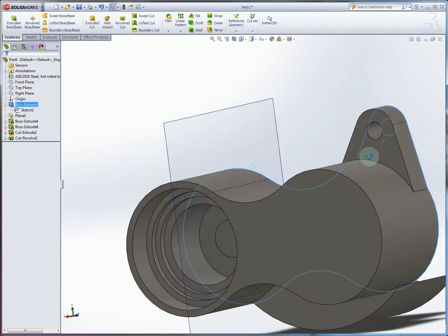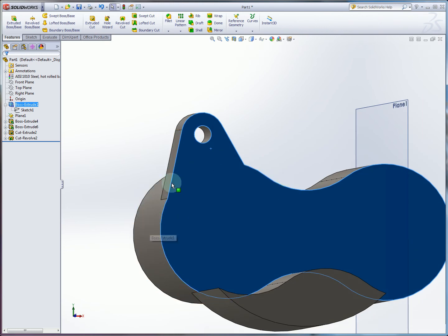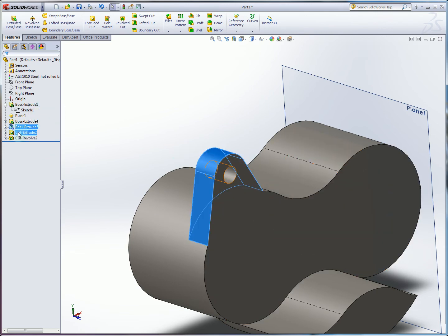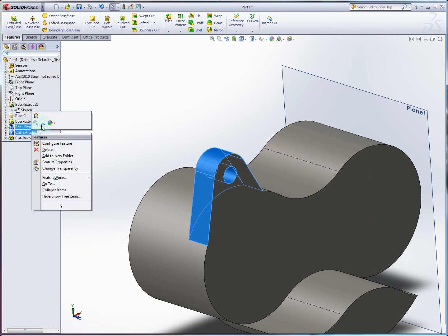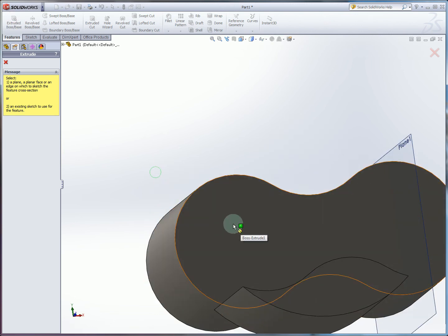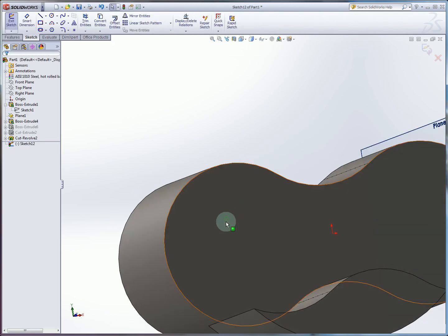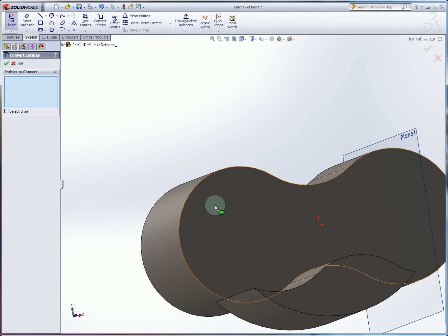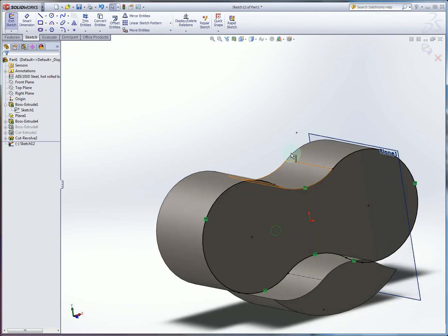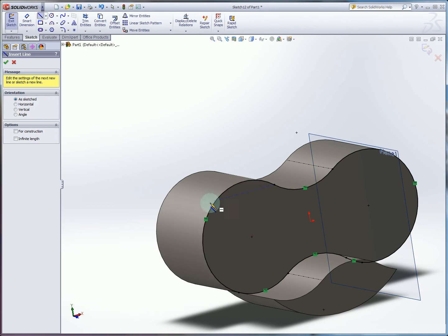So this feature is extruded along this round wall, but it brings a part out. So we have this little nub that comes out, and then we've added a hole. So if I want to make this from scratch, I'll just suppress these now. I can make an extruded boss or base. I'm going to choose this bottom sketch plane, and then use my Convert Entities tool to just select the face and click Done. Now you can see I have this black outline on my sketch that's a great starting point for any feature that I want to have stick out to one side.